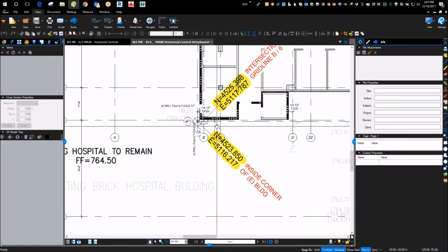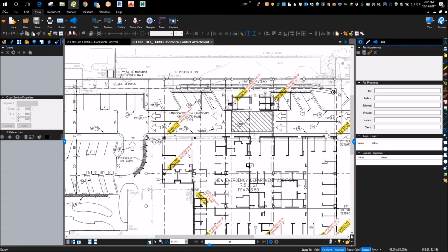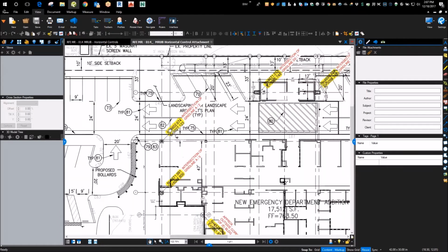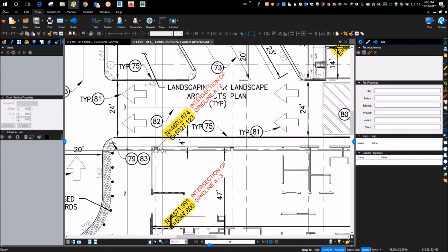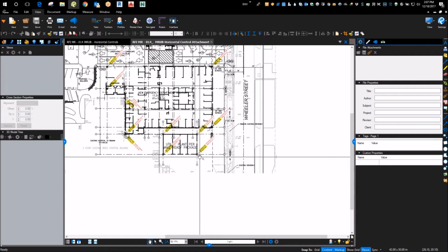So we said we need the coordinates of the actual grid intersections, and we just pasted our own from our understanding of the plans, overlaying and QCing it in CAD. We can say, hey, here's where we think you said you wanted it. Please confirm these numbers. We only really need a couple of these. A grid intersection coordinate at opposite corners of our site would do us well, but we put as many as we could, or at least quite a few, like the four corners of each building.